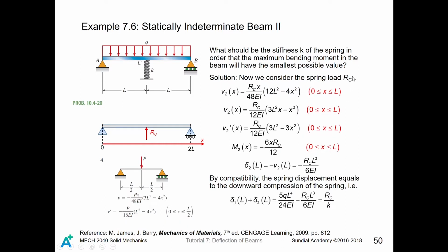After we talk about the deflection caused by the distributed load, we are now going to consider a single load located in the midspan of this beam, which is RC. So still, we put P equals minus RC, as well as L becomes 2L into those superposition table entries to get the deflection curve for the left span of this beam.